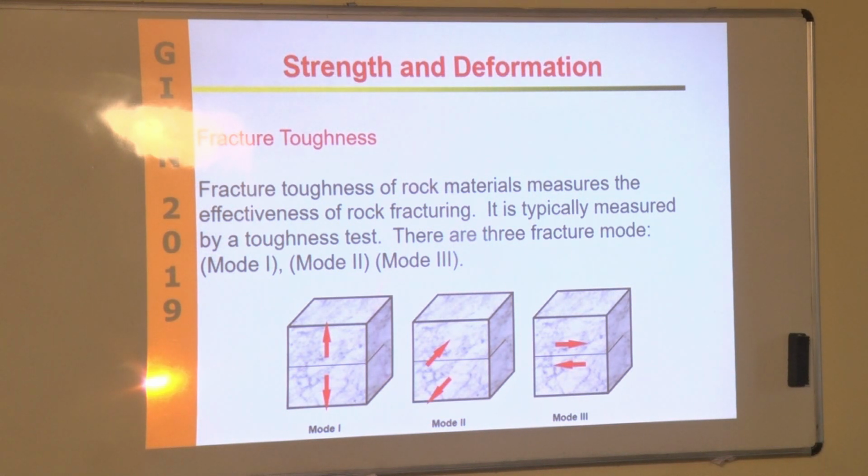Now again, me, opinionated: mode 2 does not exist microscopically; it's only mode 1. It's just a tensile displacement that creates the tensile failure that is happening. However, you can have a shear displacement that is superimposed on that tensile movement, which makes it appear that shear failure is happening.